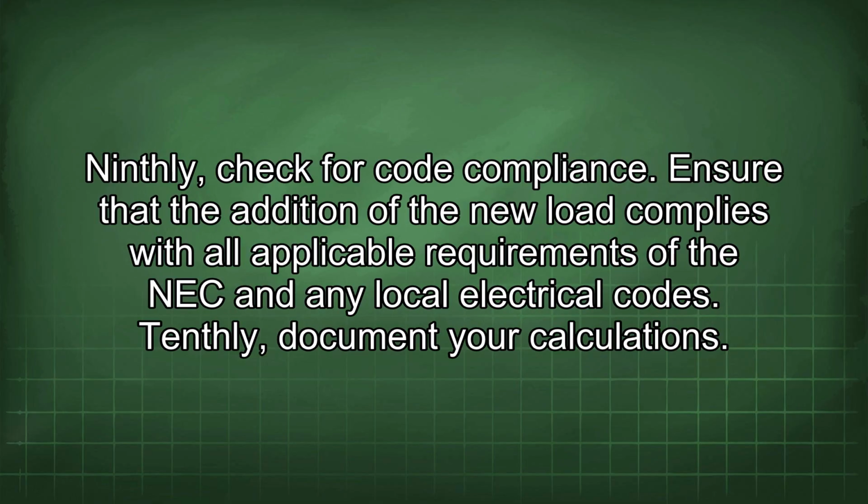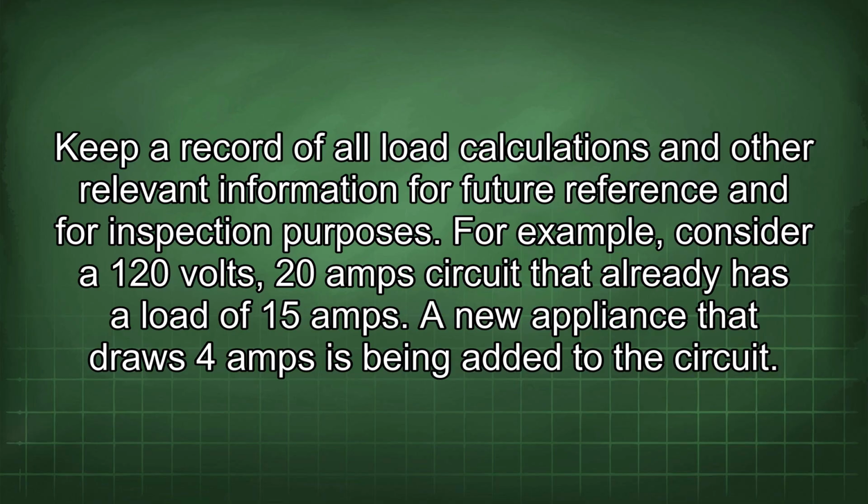Ninthly, check for code compliance. Ensure that the addition of the new load complies with all applicable requirements of the NEC and any local electrical codes. Tenthly, document your calculations. Keep a record of all load calculations and other relevant information for future reference and for inspection purposes.